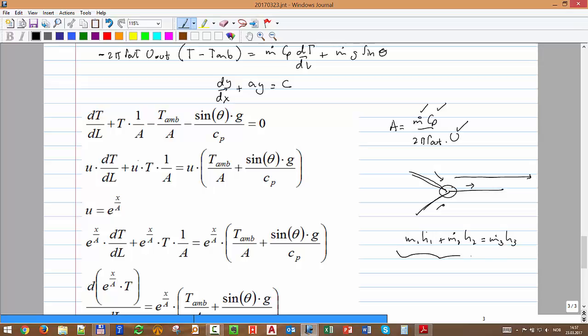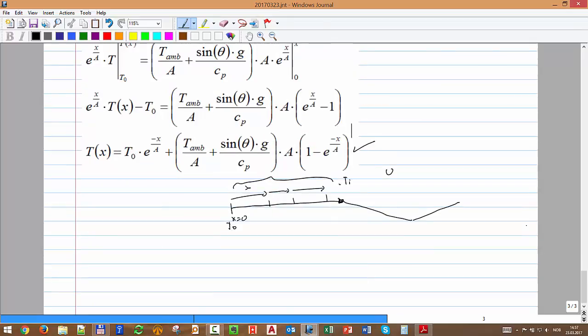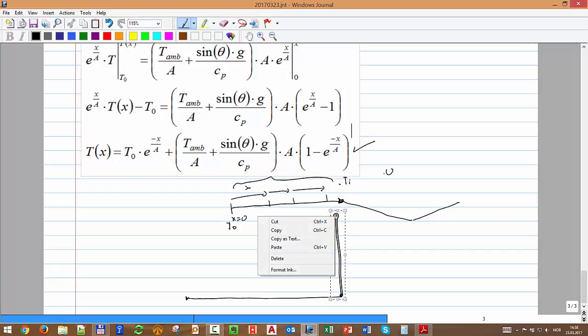That actually is something that the software has to do when you have a mixing point. You have to calculate the temperature at the outlet. With this expression you calculate the enthalpy, and you have pressure, so you can calculate temperature. But we are not going to see that. So in your exercise you have only 2 segments, and CP, I'm telling you, you assume constant, so really you have to make one equation from here to here and one equation from here to here. Okay, so the only thing that changes is the sign of that. Okay, then we are done with this temperature equation. Any question?